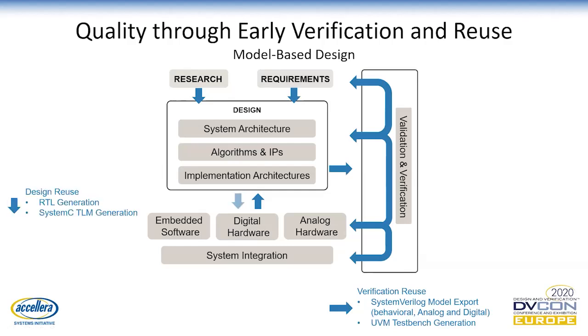Then that's not the only way to reuse models. Design models can be reused by generating RTL code and SystemC TLM models. And other EDA interfaces are available as well. And these allow to feed implementation information back into the models, like information coming from RTL or SPICE simulations or from the lab, from the measuring equipment, can be fed back into the models to make sure that models are aligned with the implementation as well as the real hardware samples that you get after tape out.